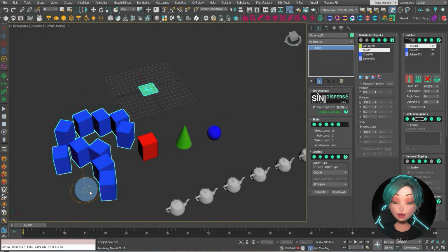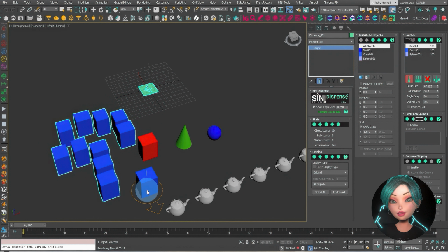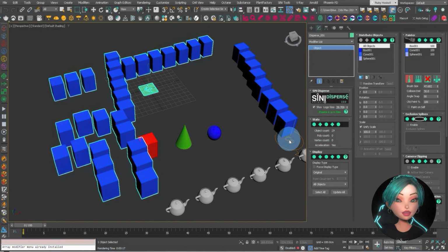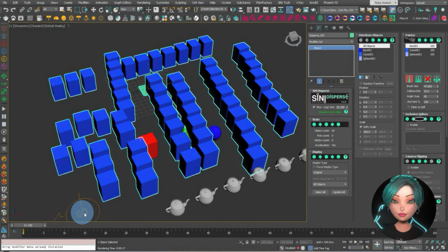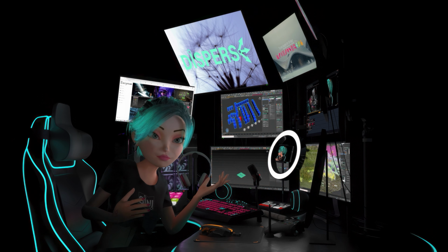Painting a few objects looks wrong. That's because I still have random transforms on. If I switch it off and repaint, you see the object direction is now set by the angle snap setting. However, I'll delete that mess.